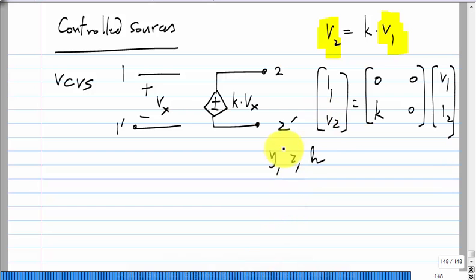If you want to measure y parameters, how would you measure it? You short circuit port 2 in some case and apply a voltage here, but then you are short circuiting a voltage source. You can't do that. Infinite current will flow. So, that is true for all three. Something or the other will be a problem. I mean, you can't measure Z parameters because you can't push a current into an open circuit. And similarly for H parameters.